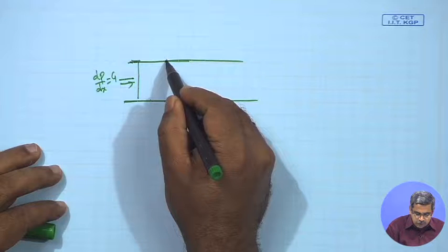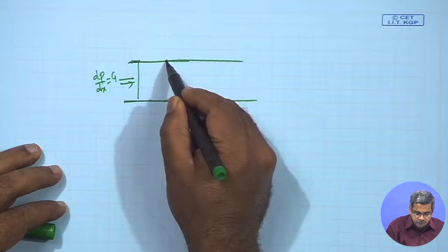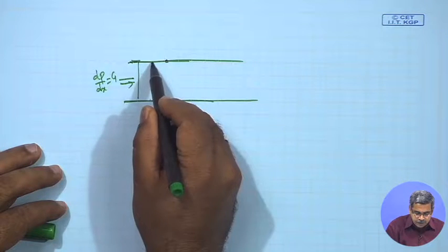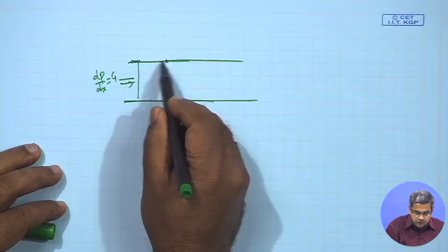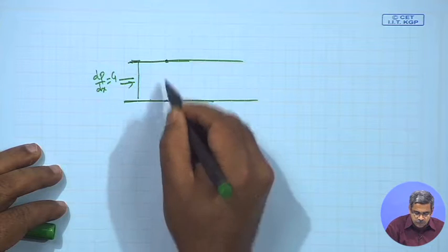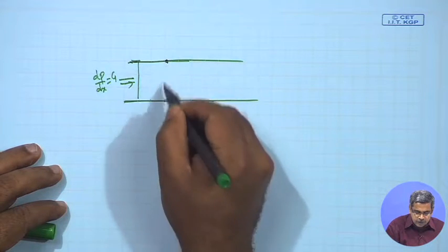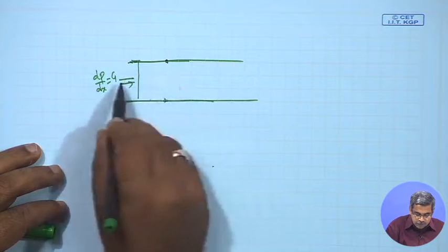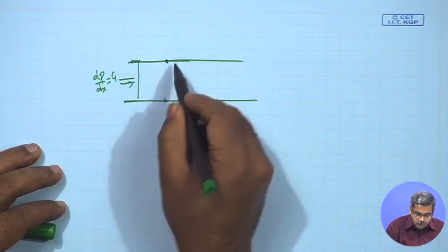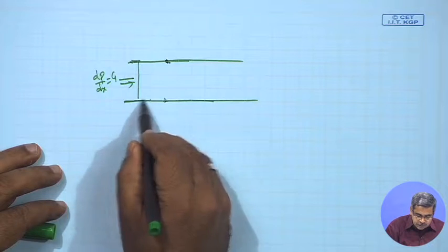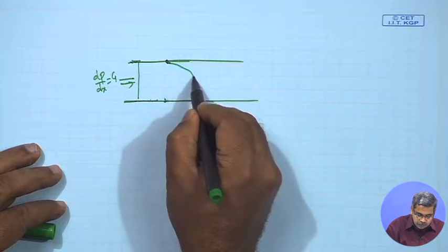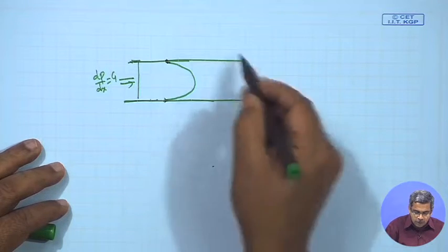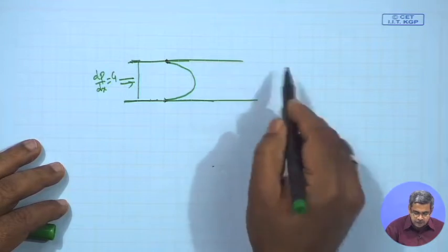Therefore, due to no slip, we expect that pressure is pushing from this side, but viscous effects are more prevalent. Since the plates are stationary, we expect the particles adhering to them to retain the velocity of the plates, but the pressure is driving the flow. So, beyond a certain distance we expect this profile. Why? Because of symmetry, right.